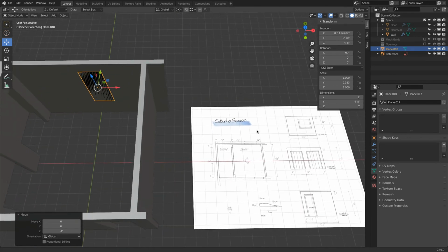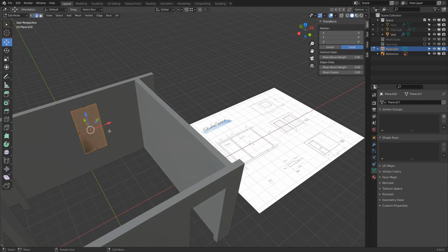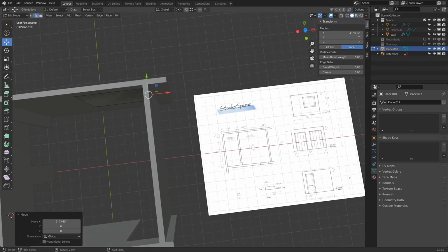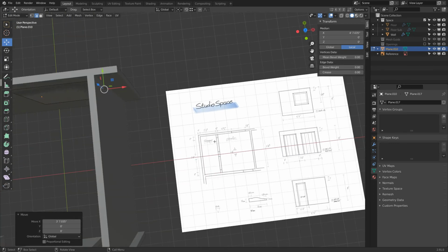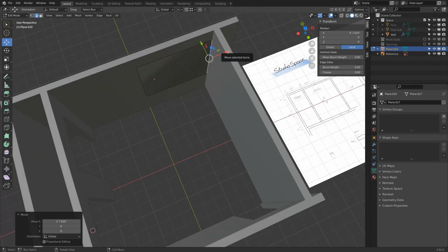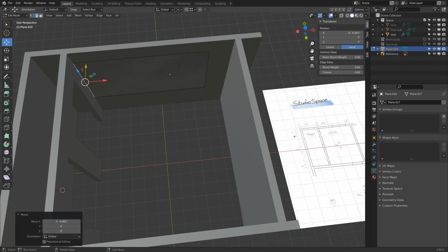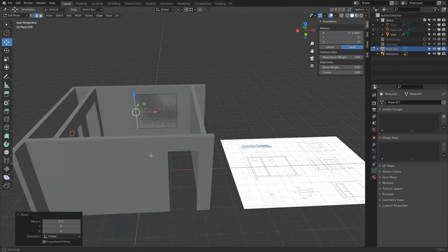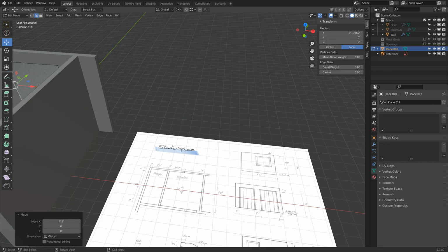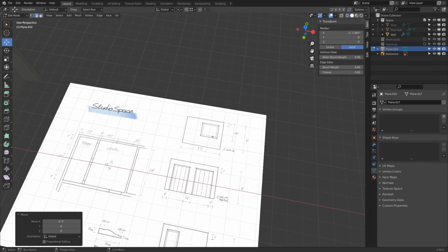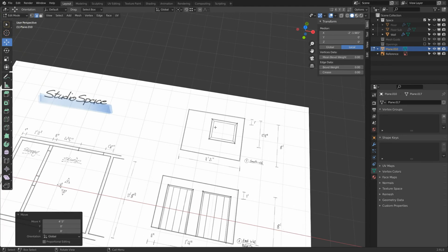So how do we do now the left and right? Let me show you a different process. This edge I will bring to there. And here it says the distance is 1 foot 8 inches. Okay. So from here, 1 foot 8 inches. There. And then from here, go to there. Snap. That is 4 feet 5 inches. Bring this back. 4 feet 5 inches. Now you see it's not really that complicated. Now this is the opening, excluding the trim, so the window itself actually will be smaller.